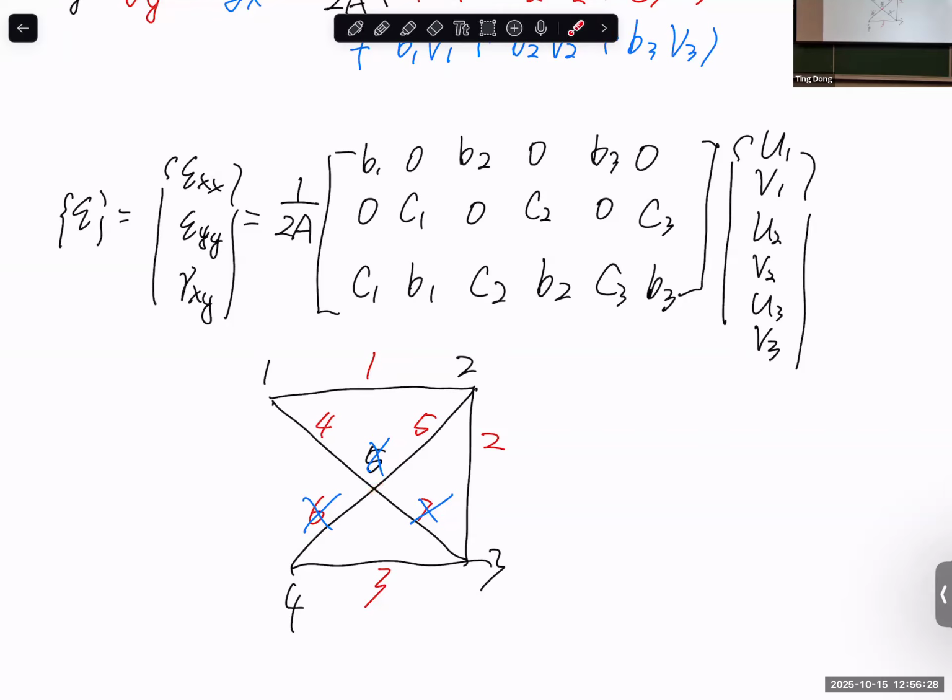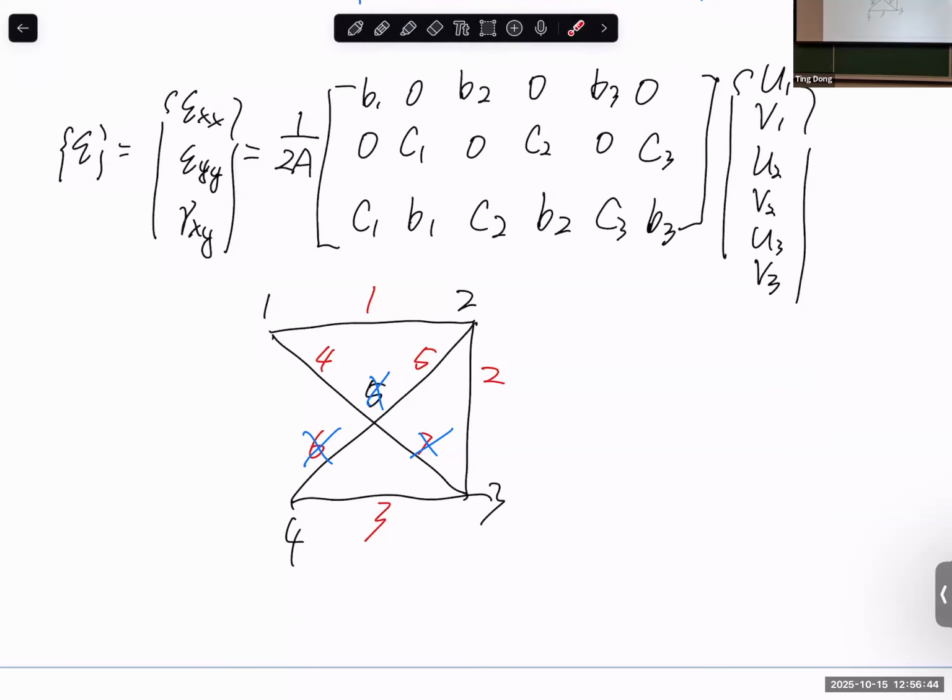And what I talked about is how to modify the input file for the node definition and element definition. And of course, in the node set and element set definitions, you also need to make changes. Let's say originally they put the element set from all these 7 in one set, or let's say if the diagonal has a different cross section, then you probably put this one in one group.